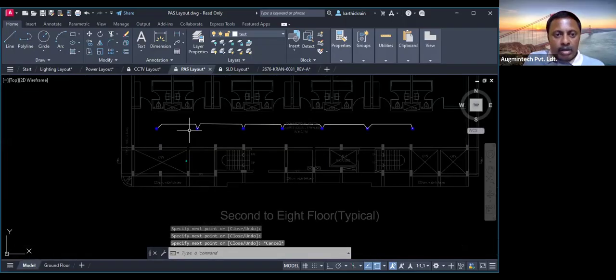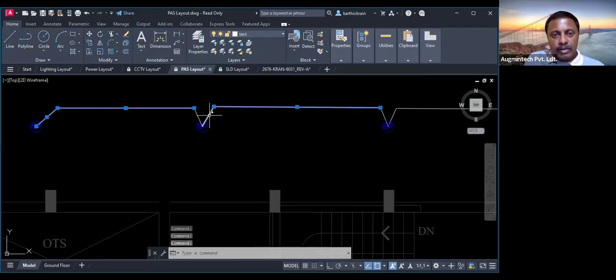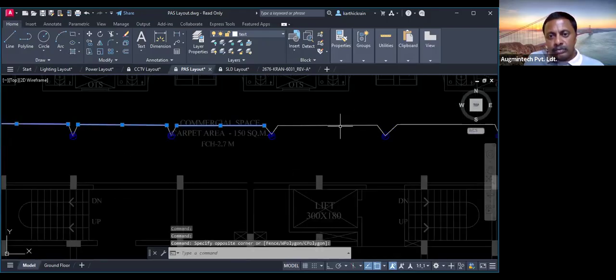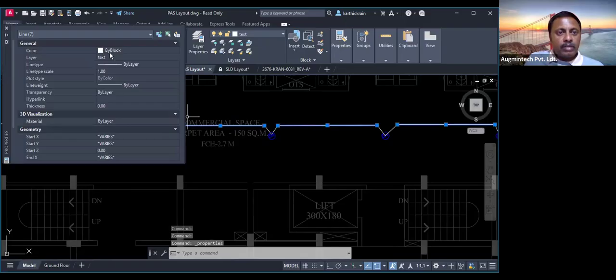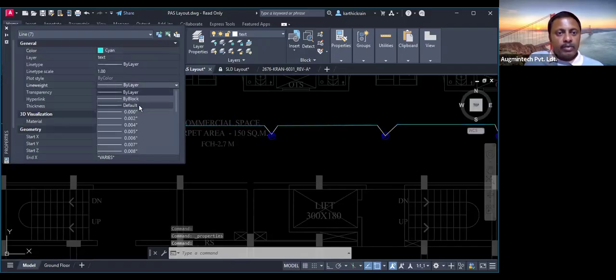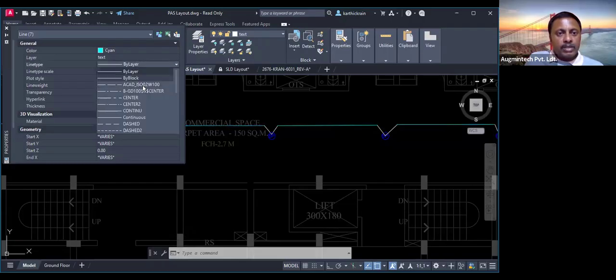All right. So here you can just change all these things. Okay. Just select all these things and you can change the color, whatever you like. Okay. That's just a sample I'm showing you. So it's nothing but just in the properties. Right. So you can right click and in the properties, you can check it out, like block, I mean, the color you can provide and layer also, like line weight. If you want to change, you can change this, right? And maybe line type you can change if you want. Okay. So that's it, all depends.